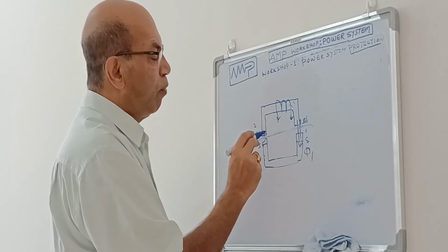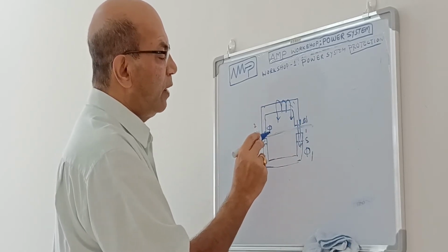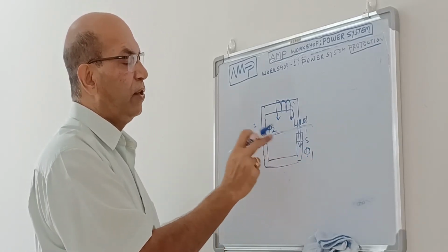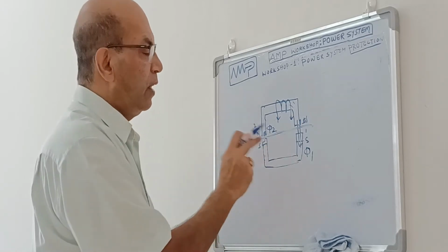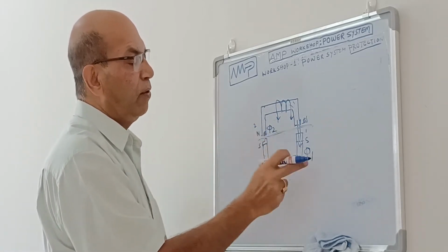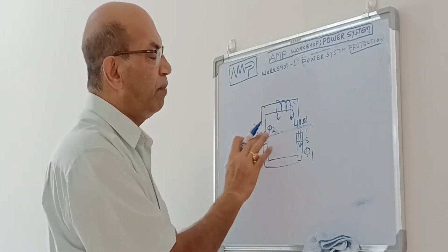So that's why we make the pole shape different, so that the magnetic flux passing through this phi2 will be in a different phase, with a different magnitude from phi1. That is the intention of making this split phase. So if phi1 and phi2 are two magnetic fluxes, they are not the same: they have different magnitudes as well as a phase difference.